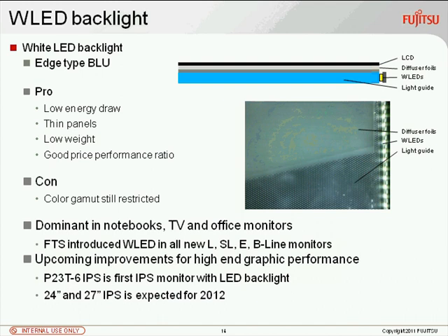So this is the principle of this LED backlight. Advantage is low energy, of course. It's very thin, much thinner than the direct backlight unit, very low in weight, and it also has a very good price-performance ratio. So we are currently at the time that the LED panels come into the same range of cost as the former CCFL displays. They come into the same performance. So now is the time, in this year 2011, where there will be the big switch in the market from CCFL to LED backlight.